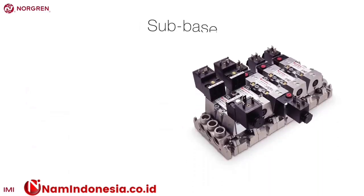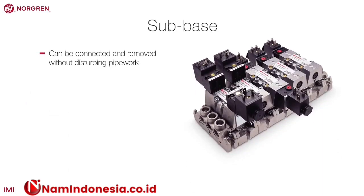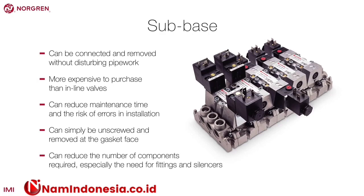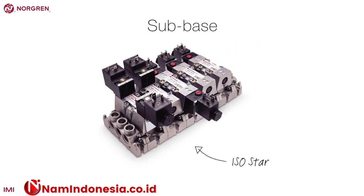A sub-base allows valves to be connected and removed without disturbing pipework. Although more expensive to purchase than inline valves, they can considerably reduce maintenance time and the risk of errors in installation. The valve can simply be unscrewed and removed at the gasket face. Sub-base valves also drastically reduce the number of components required, especially the need for fittings and silencers, as compared to an inline valve. Norgren's ISO range is an example of a sub-base valve.